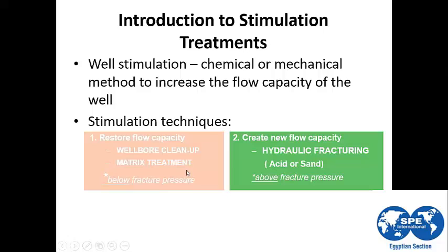The same idea applies to hydraulic fracturing. With hydraulic fracturing, you are creating a new channel inside the reservoir to allow all the reservoir pore spaces to produce in a highway channel, as we can say, to make a highway contact between the wellbore and the pore spaces inside the reservoir.